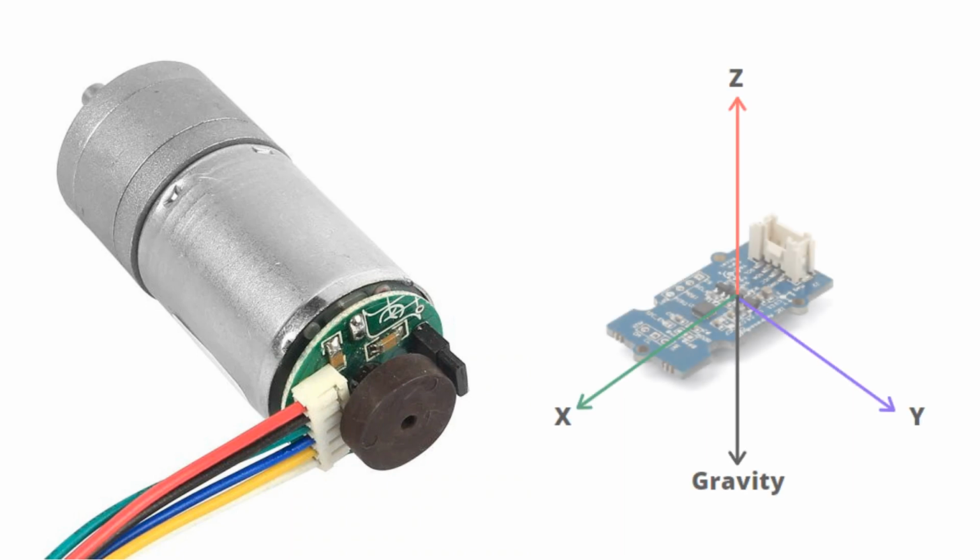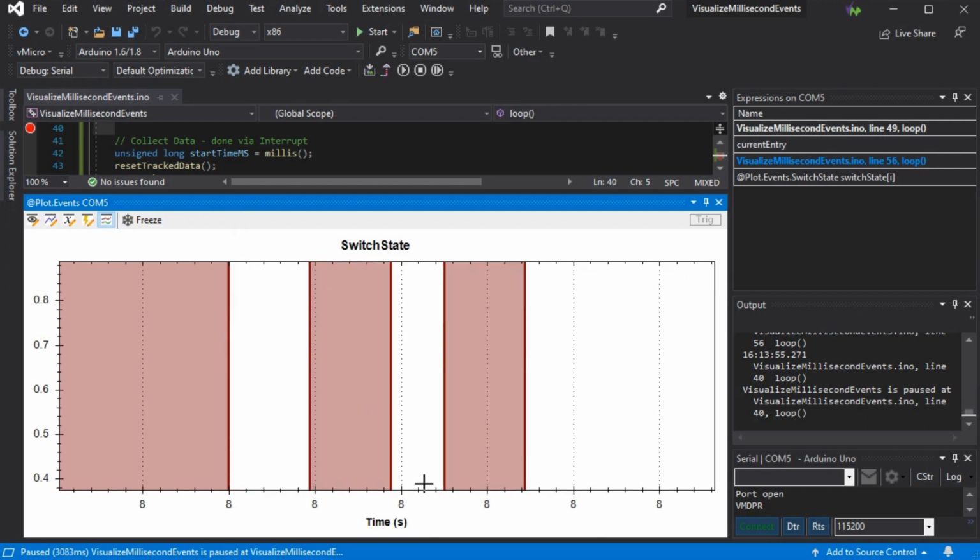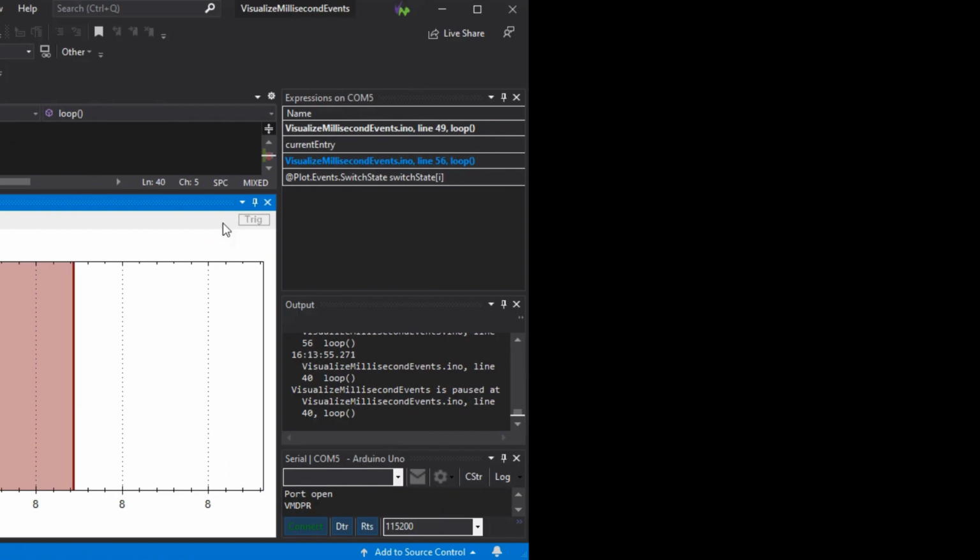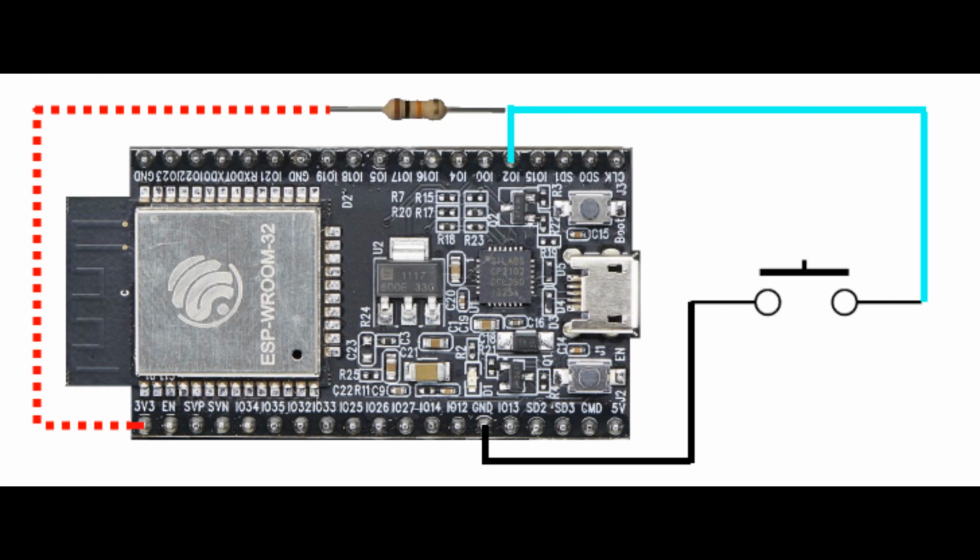The advantage of interrupts over digital and analog read is they execute when something happens, not when your code reaches it, meaning you can now track milli and microsecond events even when your code is doing something else. Here we're going to show how to set up a simple interrupt on a single pin to track when a button is pressed, and then debounce it in software without additional hardware such as an RC circuit.